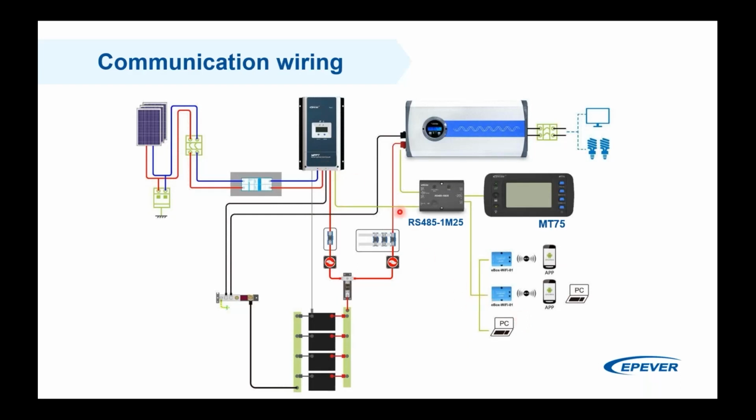So these cables are not really carrying a large amount of amperes or voltage. They are just signal lines. And the protocol is Modbus. So Modbus is a 2-wire, or arguably 3-wire, communication system.